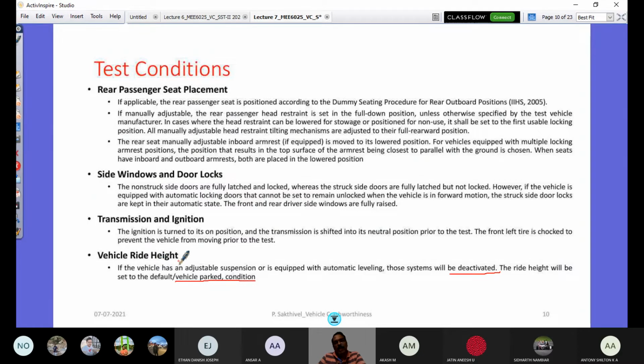When you drive your vehicle, you want to have your three important objectives of isolation, rattle space, and road holding. So a semi-active suspension system is better suited, but that would work only while driving the vehicle, not when it is stationary. So the test condition should have any active suspension system deactivated.